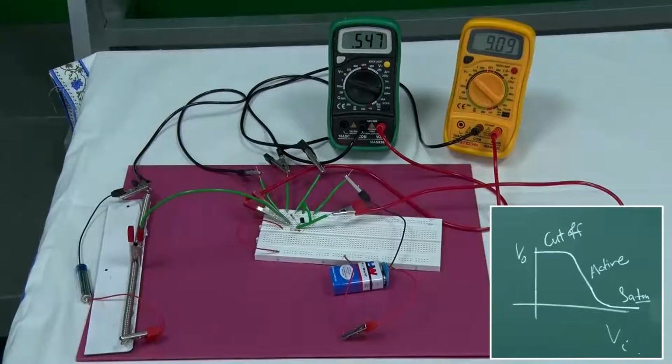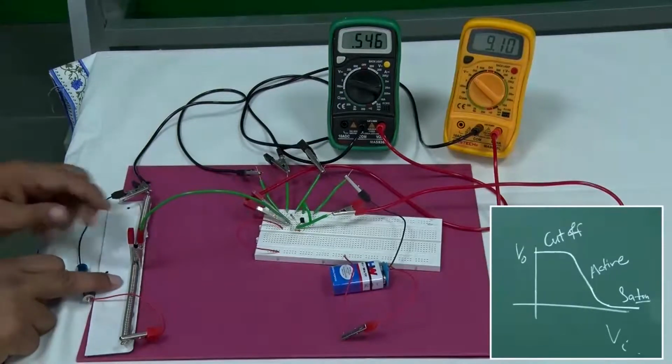The transistor is now conducting, the collector is doing some job, there are carrier injections from the emitter to the base, there is some IC, and there is some RL into IC drop on that 10 kilo ohm resistance, and therefore, the output voltage of the collector has gone a little bit down. Again, increase it further.